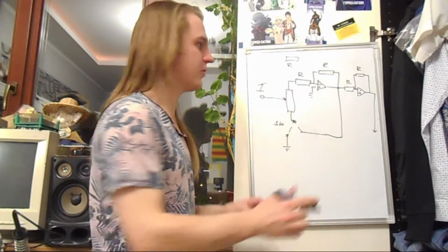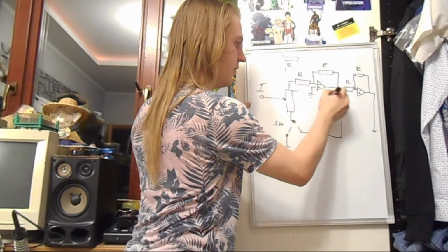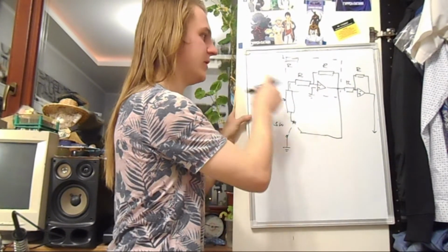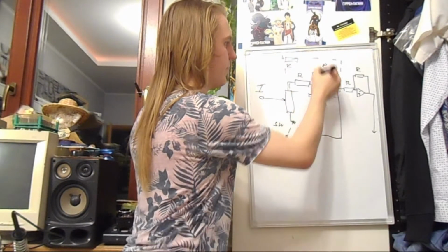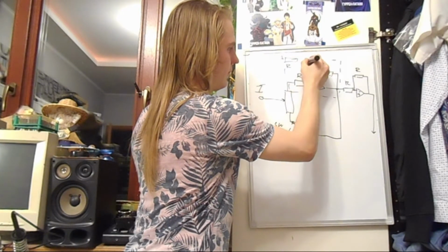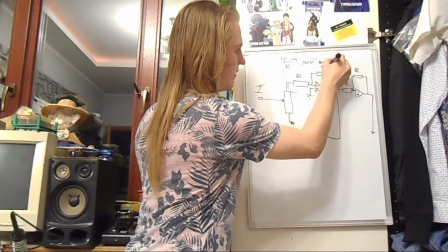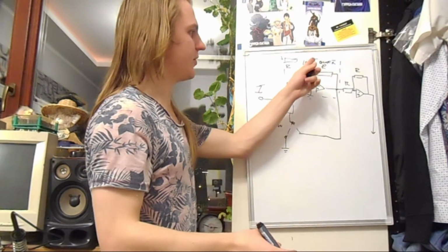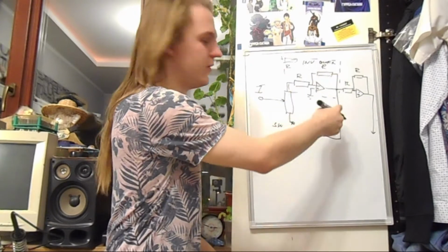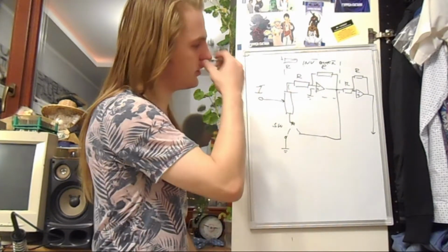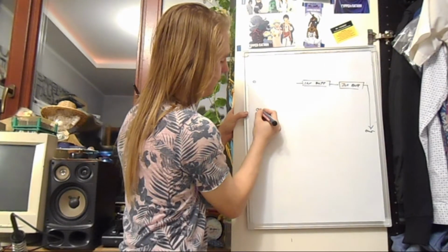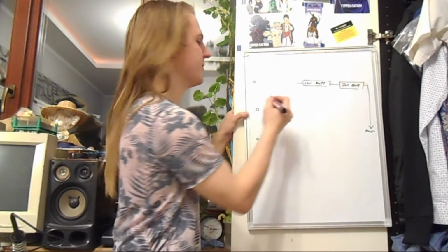But first, let's call this piece of circuit the inverting operational amplifier with a gain of -1 and inverting buffer. So whenever I put this into the circuit as a box with an input and output, you know that it's just an op-amp set in this inverting amplifier configuration with the gain of -1. So now we have our input 1, input 2 and input 3.